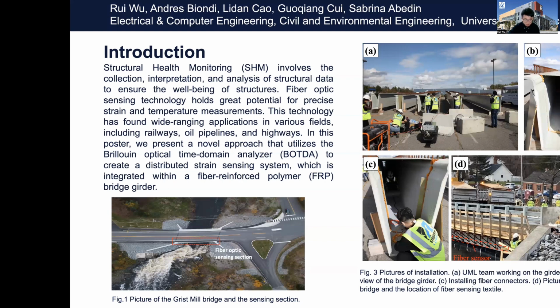By measuring the Brillouin frequency shift along the entire length of the optical fiber, BOTDA can provide precise spatial information about changes in strain or temperature. This distributed sensing capability allowed us to monitor structures in real time, detecting and pinpointing potential issues, making the BOTDA a valuable tool for ensuring the safety and integrity of various infrastructure systems.